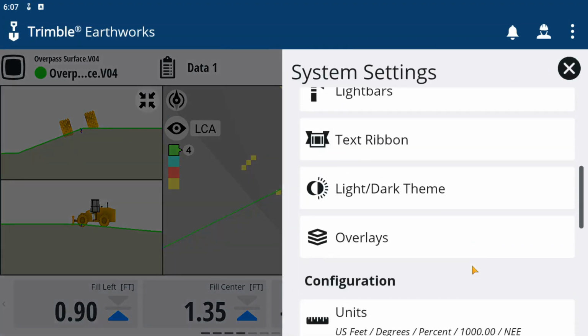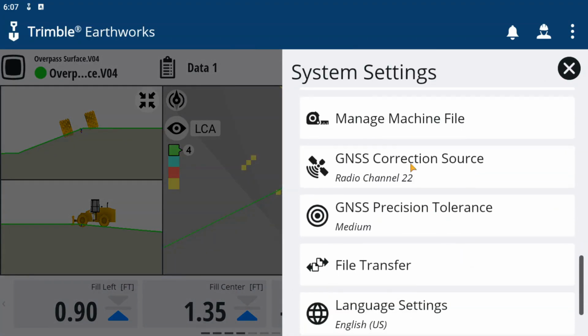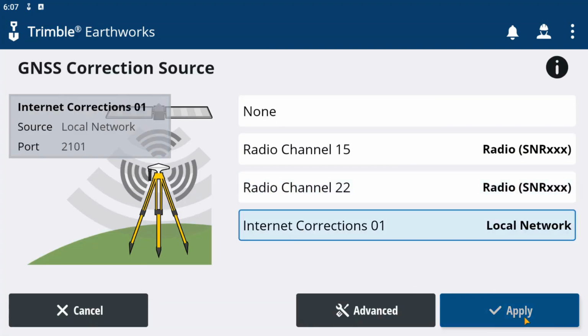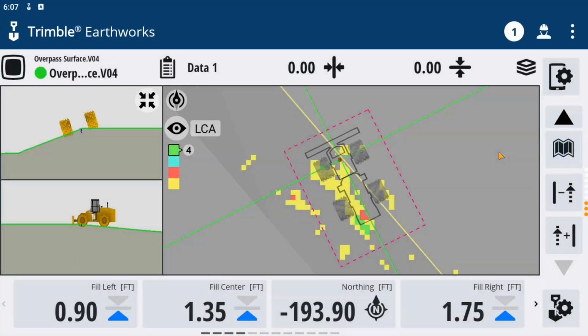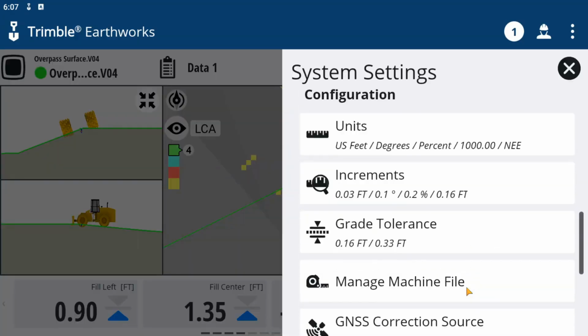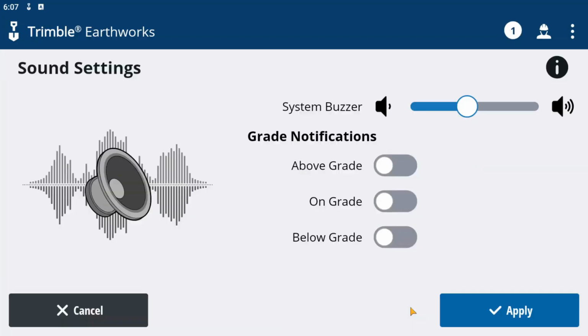Please note, it is not advisable to change any setting relating to GNSS tolerance. You cannot make a GNSS system more accurate by adjusting a setting. You will only be adjusting your tolerance to the errors you're seeing. This could cause potential issues going forward. Consult with your local technology support specialist before making any changes.